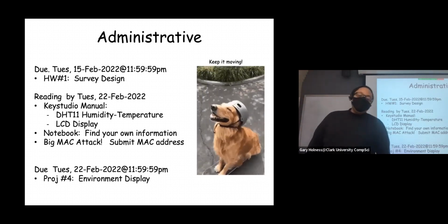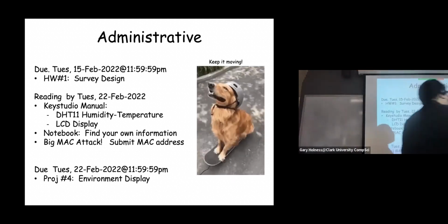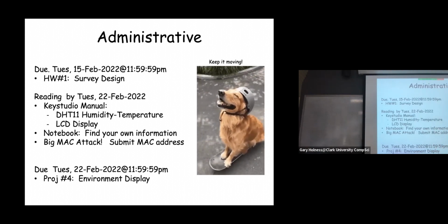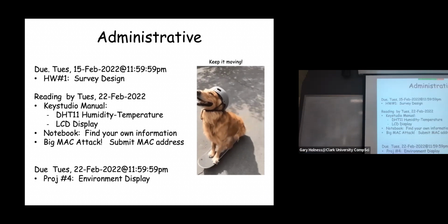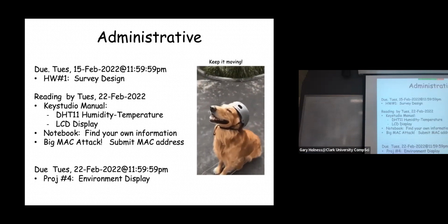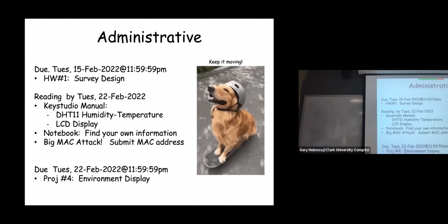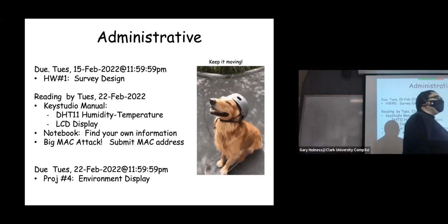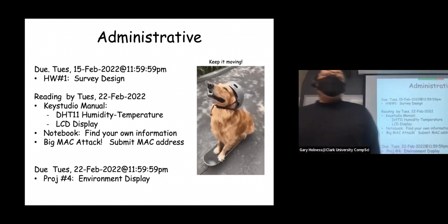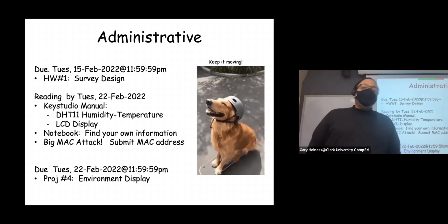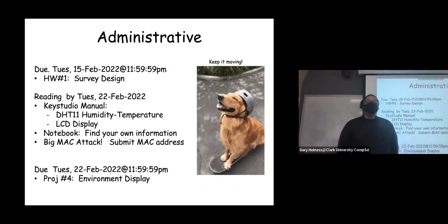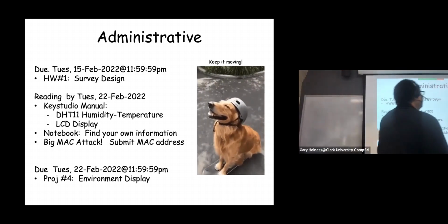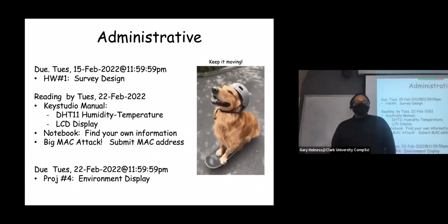The reading has changed. This is where I remove some of the scaffolding. I step away and do a little bit less for you so that I can, quote unquote, teach you how to fish. When you integrate various components, many times there's not a textbook and you have to read between the lines. You're going to get information about components from the data sheet, and that data sheet might be for the component itself or a very closely related component, because many of these things support a common protocol. That's actually the case with the LCD screen, and we'll talk a little more about that in the subsequent slides.